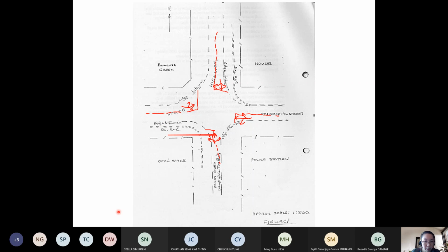All right, so you can make use of, say, you put a traffic island over here. Okay, I don't want to allow this movement, so I channel them into this and so on. So you put a traffic island, this traffic island or painted island. Okay, something like that. Or I can allow a straight median like this, a strip island, for example. Sorry about the bad drawing. Something like that. All right, so that means I give priority for this movement to go here.